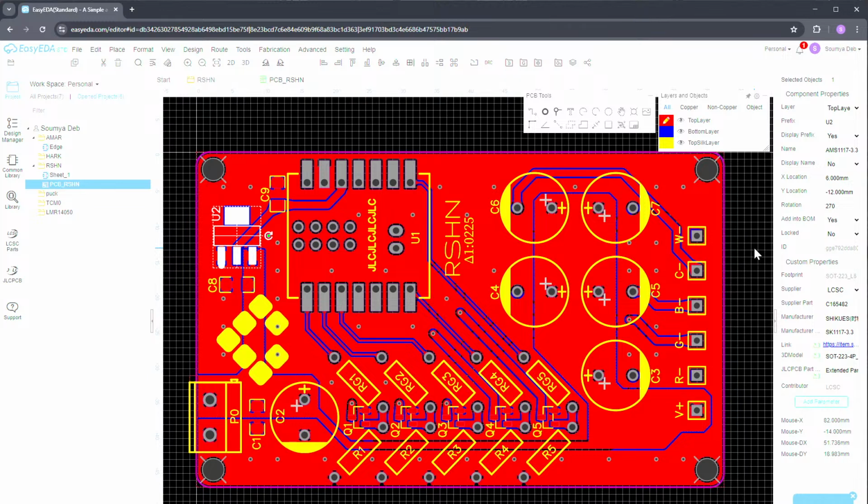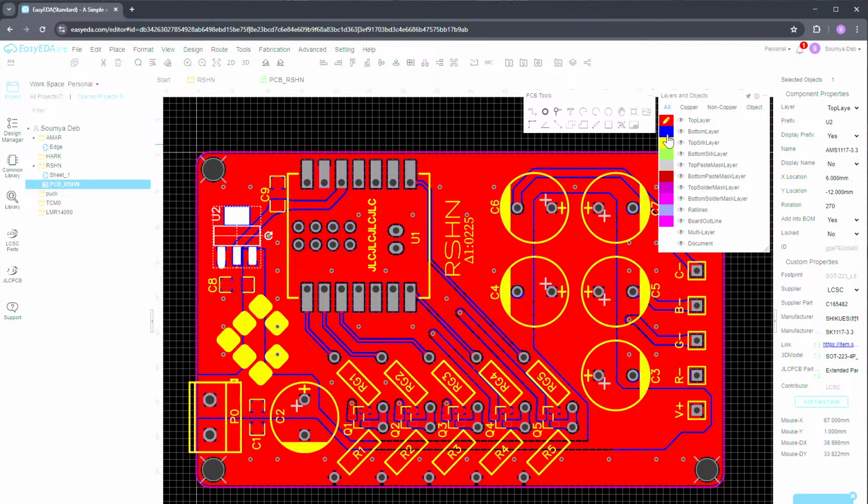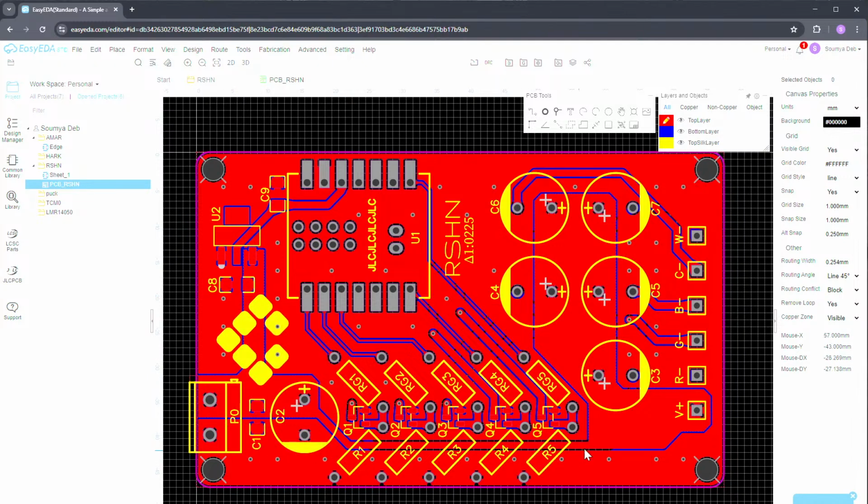All right, cool. The point I was trying to make is that because of just two layers, tracing is hard because you cannot cross over or jump over something. With 4-layer boards it is much easier. It's only 2 times as many layers, but you get about 4 times the flexibility in tracing and routing your traces. But I was intentionally trying to keep it simple. So that is done. Next board would be 4-layer.